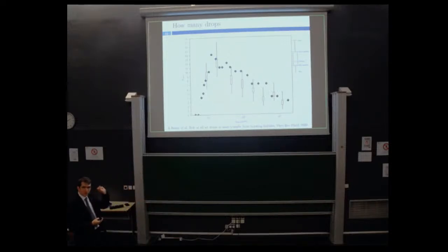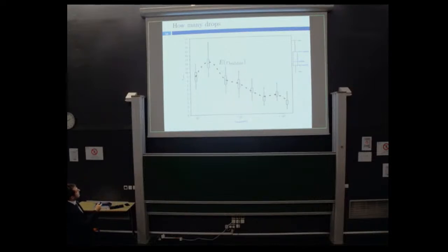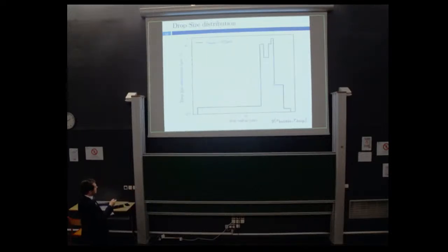So to characterize the number of ejected droplets, I will only consider the statistical distribution here, and by doing a convolution between each distribution for each bubble size, we get the number of ejected droplets for a given bubble radius. So we've got the bubble, we've got the number of ejected droplets. We then need to statistically characterize their size. So again, here for each bubble size, we can measure the droplet size.